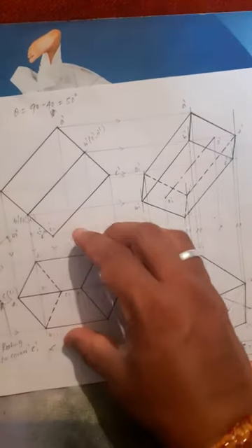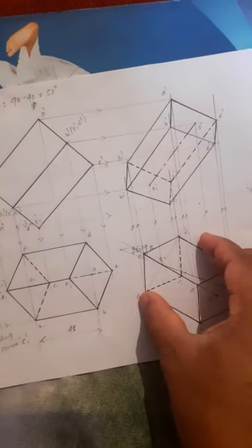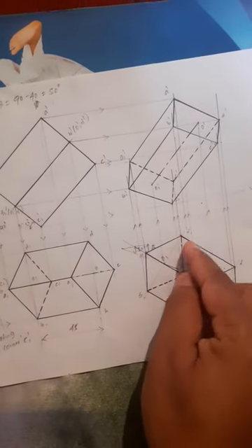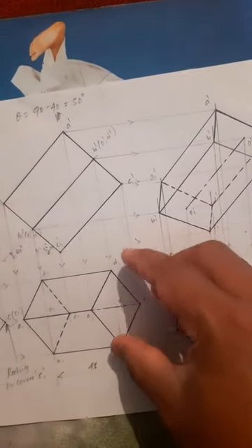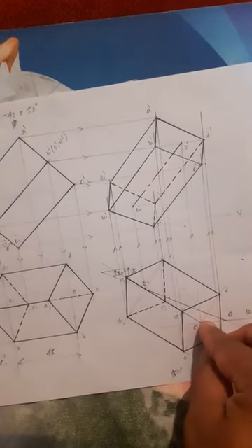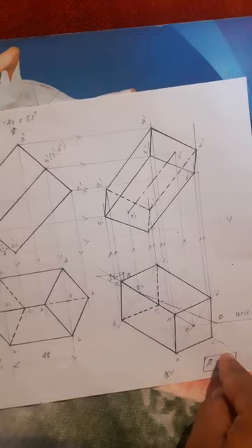Just rotate the solid placed on the beta degree line. Now if you rotate, above the beta degree line D1 will come, below the beta degree line B1 will come. Right? Similarly, apply the same concept for the top face placed on this point. From this O draw a 90 degree line and continue the beta degree line.